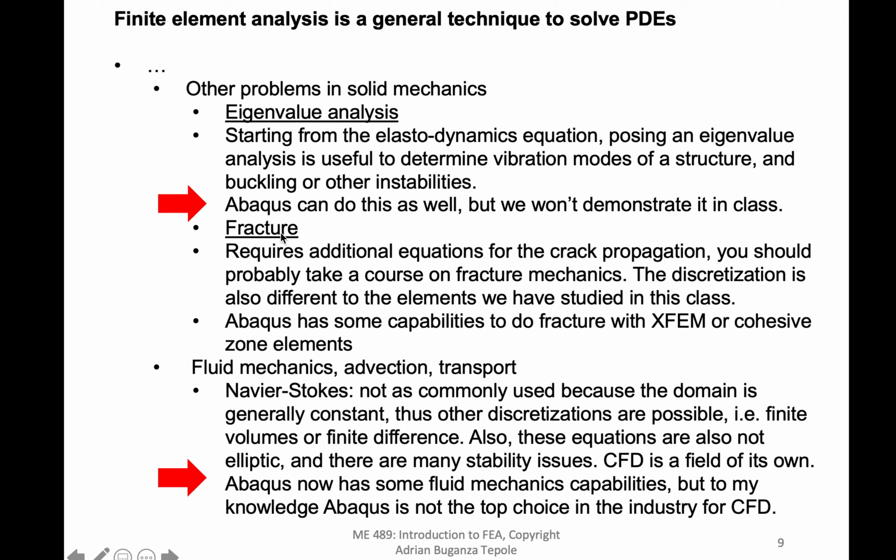Fracture. I don't know if someone asked me about fracture. That's also something that you can do with Abaqus that we have not done. So again, we have restricted our attention to the part of the deformation that is linear elastic. But if you are interested in crack propagation, maybe take some class on fracture mechanics. Here you need to have different types of elements. Abaqus can do this with either something called XFEM or cohesive zone elements. That's something that I use in my research. So just keep in mind that Abaqus can do it. You probably need a little bit more information.